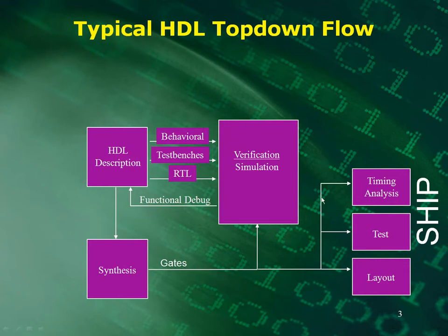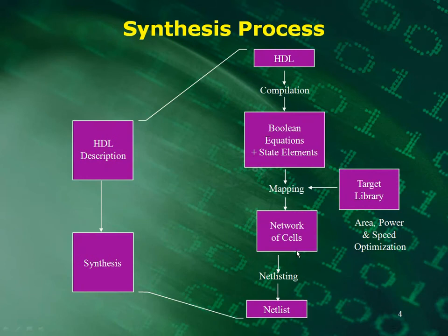Then you're probably going to want to do some more testing. If you're doing an FPGA or an ASIC, you're going to do this. If you're doing an FPGA, you'll be doing this a lot. If you're doing an ASIC, you may have to go through some layout tools, and eventually you're going to ship this thing off, and then you're going to have to test it when it comes back if it's an ASIC.